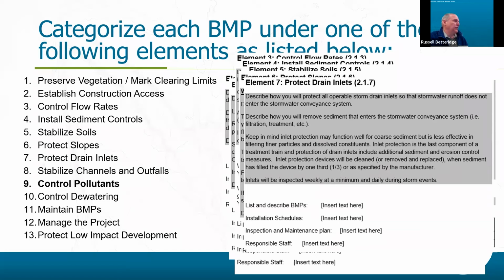Protecting drain inlets. Of course, this is where you really get into that bark bag or the sediment sock, or, you know, you get into a manufactured product that starts to help you once your inlets are in place, or if you have existing inlets you're working around, what are you doing right up front to protect that inlet and that really that discharge point from your project?